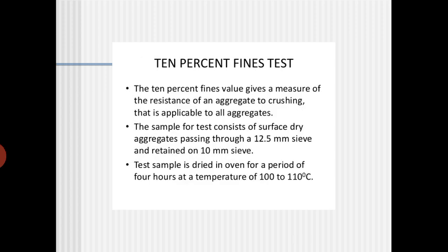So then, the 10% fines test. This is also one kind of test that we are going to find out. What does 10% stand for? In this test, we will take some quantity of aggregates, and those aggregates should pass through a 12.5 mm sieve and be retained on a 10 mm sieve.